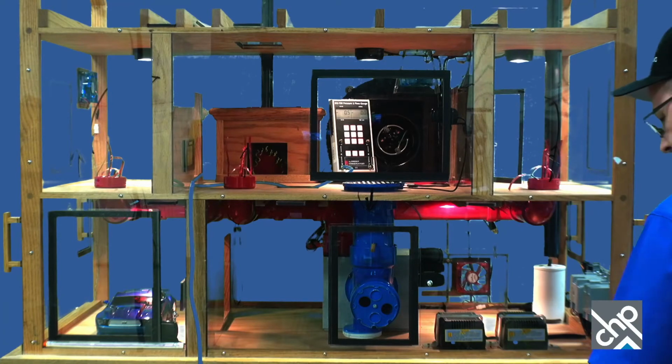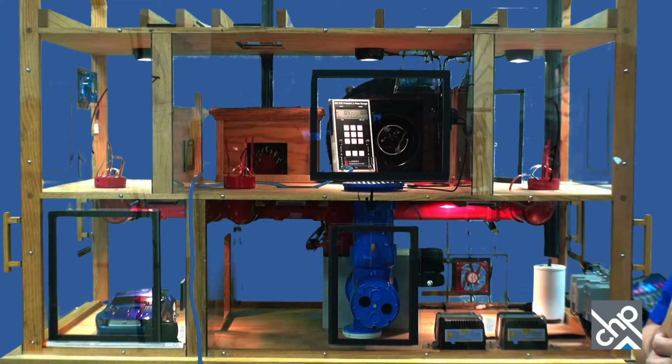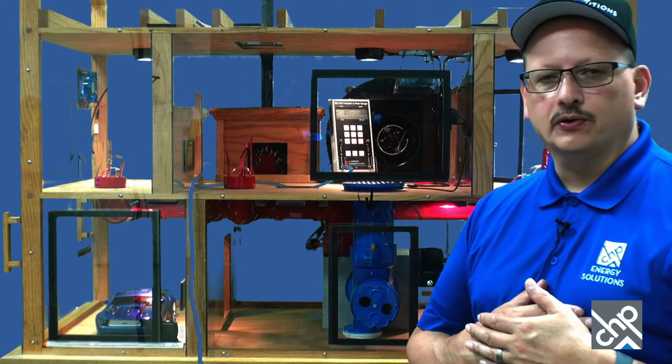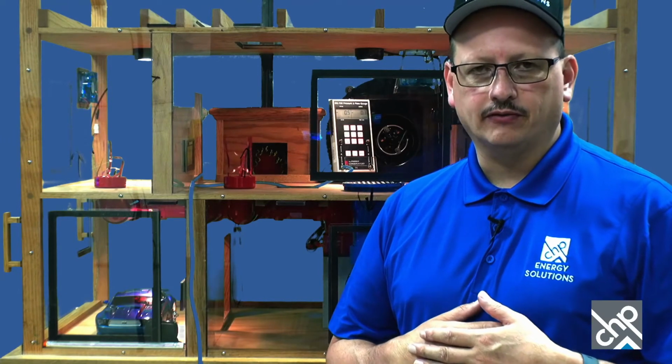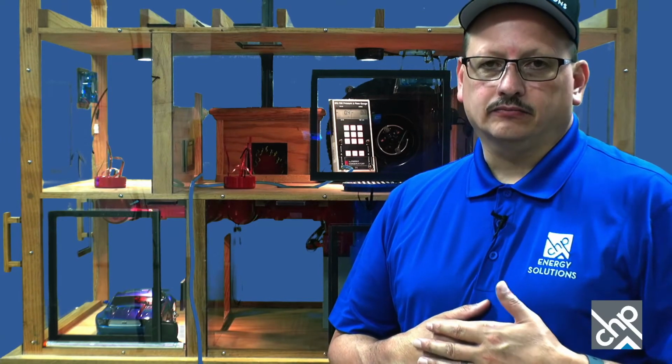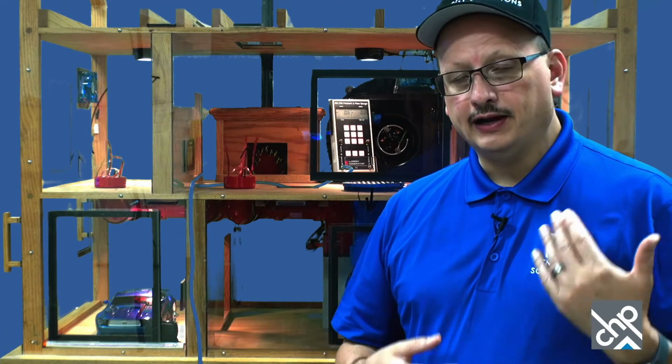So what happens though when you start closing the doors? When you start closing the doors, then again, depending on the tightness of the house and the individual rooms and how much airflow is going into the room, it can create some comfort problems. It can also create enough pressure to maybe cause some backdrafting, maybe like a water heater or something like that.